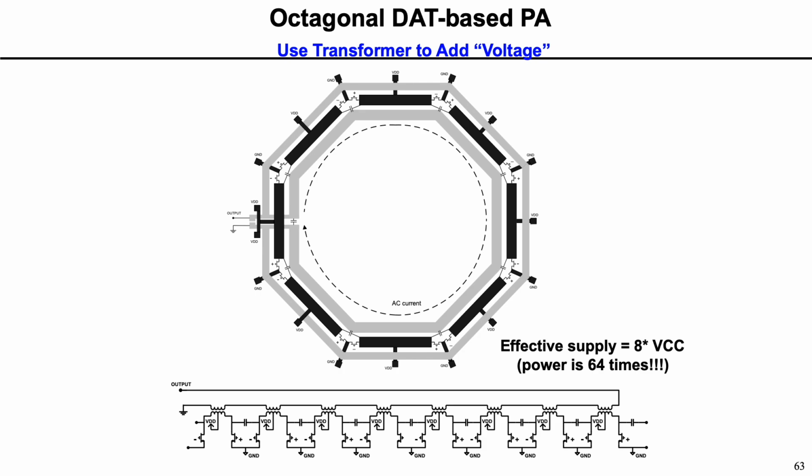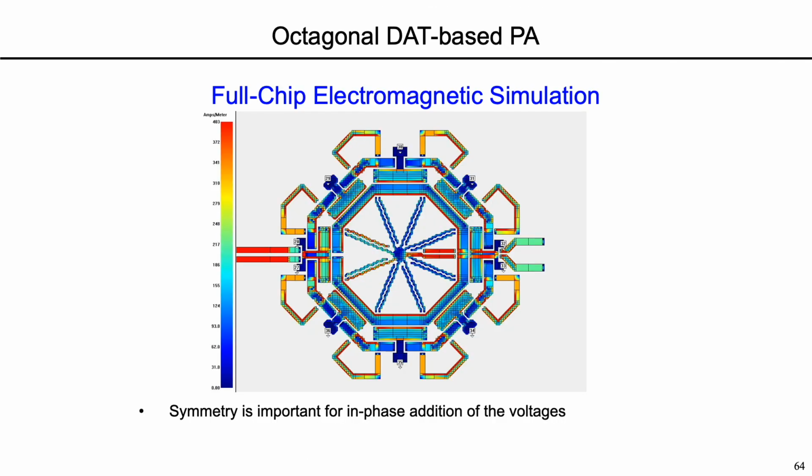Another fun example is that you can actually make an octagonal one. You can make any kind of polygon. An octagonal one will have 8 cores to drive it, and they are in series. So this is an example of an octagonal design that was done with a different kind of distribution network. This is a picture of the die made with that octagonal design.